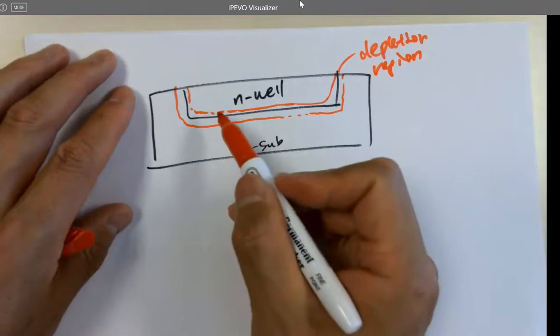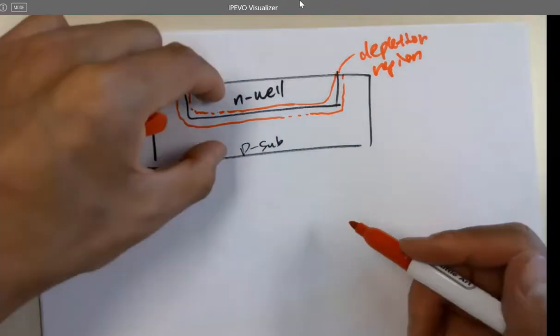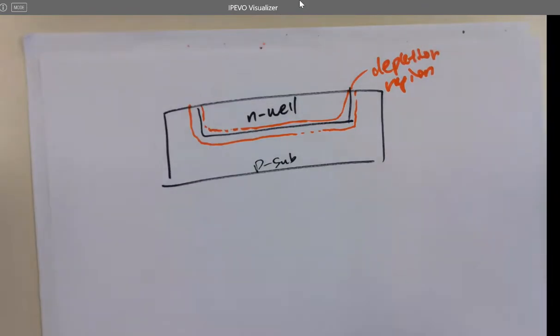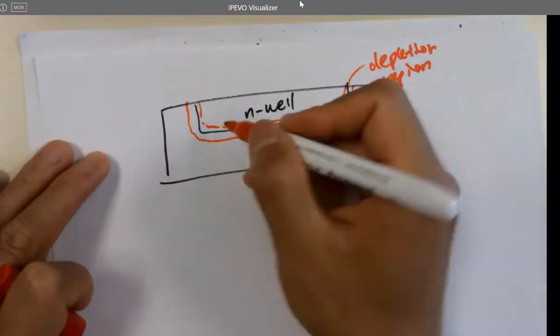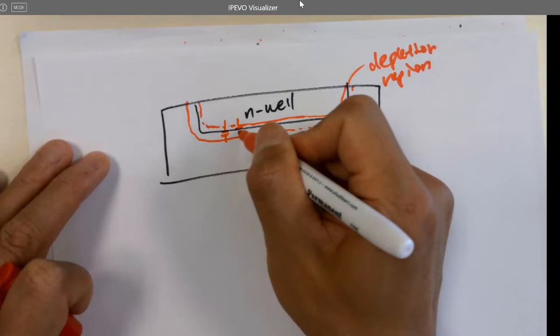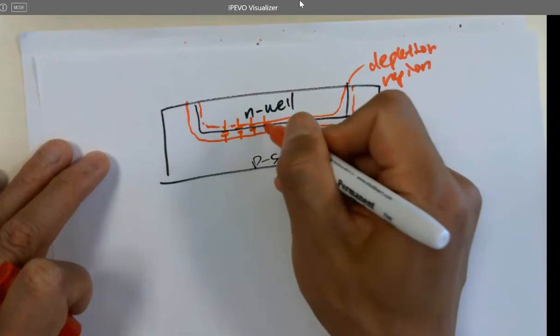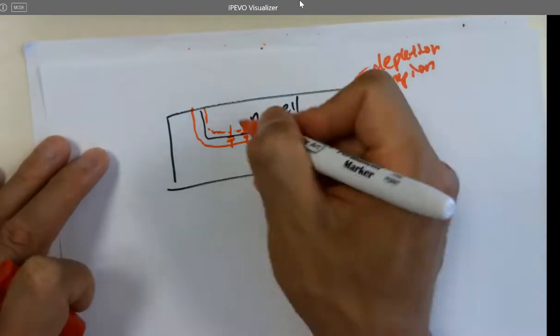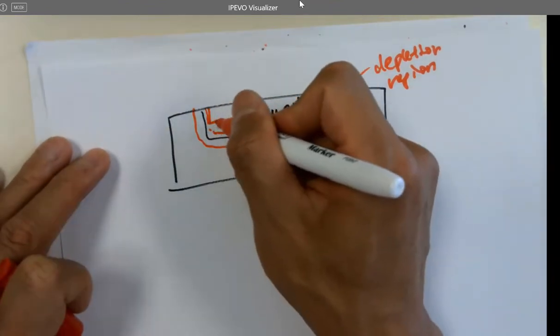And remember, if you have a higher voltage over the depletion region, are you getting a thinner or thicker depletion region? Higher forward bias voltage, thinner, right? Because whenever the forward bias voltage is high enough, you can make a thin enough depletion region so the electrons just tunnel through, and you get a current flow. But still, there will be parasitic capacitance over here, like how we modeled it. And because the N well is a resistor, there are resistors here as well.